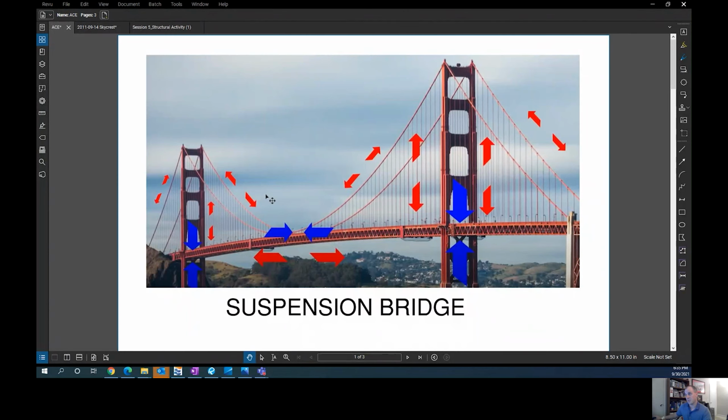In the suspension bridge, all the tension is primarily carried by the cables. You have two primary cables that are shown here as the curved or smiling cables, right? And you have your secondary tension elements, which are the vertical cables hung from the primary tension cables. Those are all these guys. The big cables, the smiling cables, again, are comprised of a lot of small cables wound together. And by doing that, we develop friction, which in turn yields us a higher tensile capacity overall.